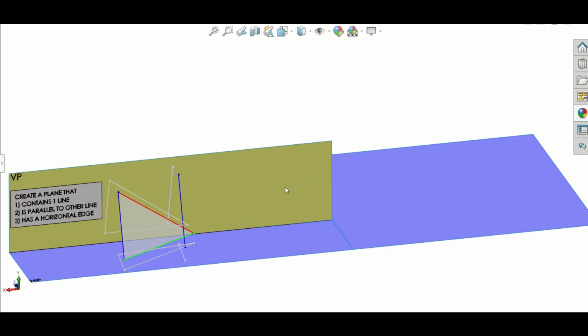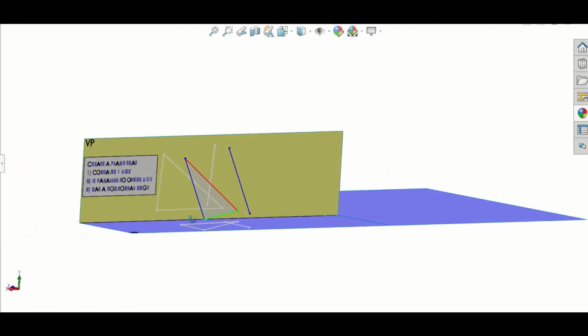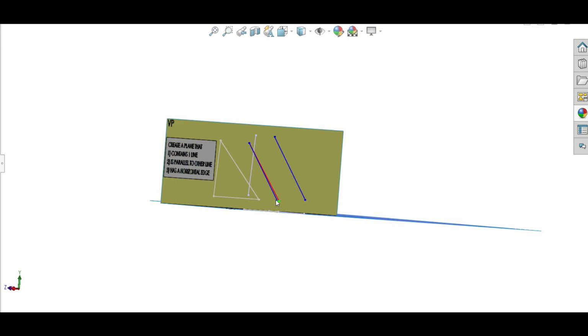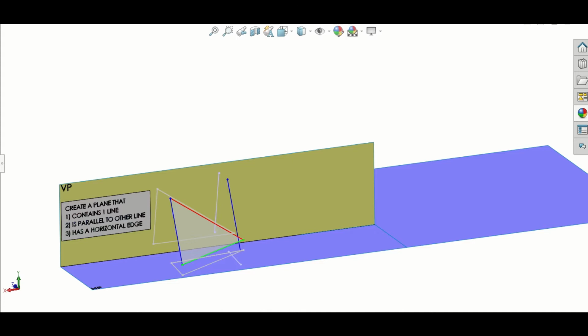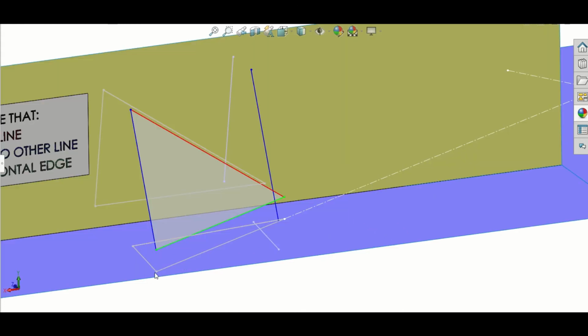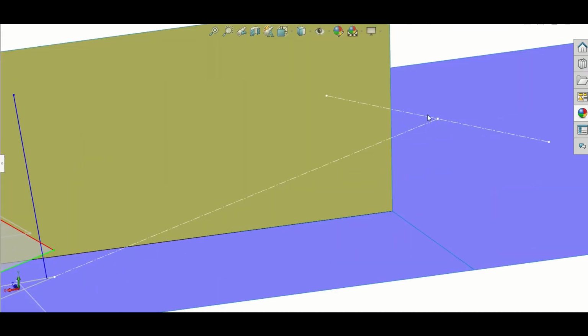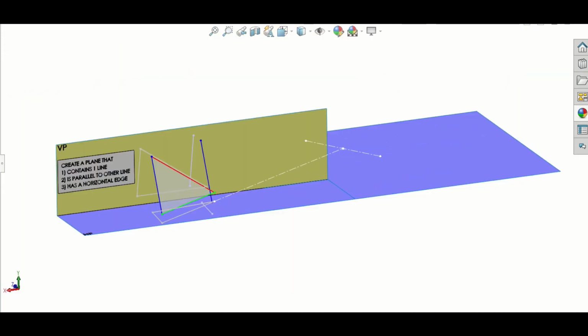Now, I have just extended the horizontal plane because I need to do what I just did there in 3D. I need to take a view that views along that green, that horizontal line, which is a true length line on a plane. And I project up. Now I'm projecting here from that green line in plan, up through and stopping at a point, and I'm going to have to drop in an auxiliary plane, an AVP right there, auxiliary vertical plane.